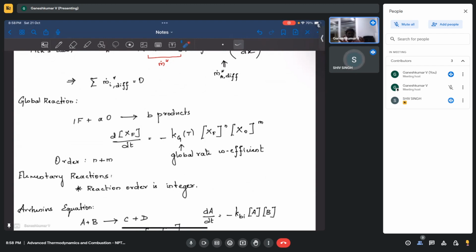You have to make sure that this reactant completes within a certain time. So how do we know that? The adiabatic flame temperature or heat of combustion will not give you the rate at which this reaction happens. That's why we study chemical kinetics.